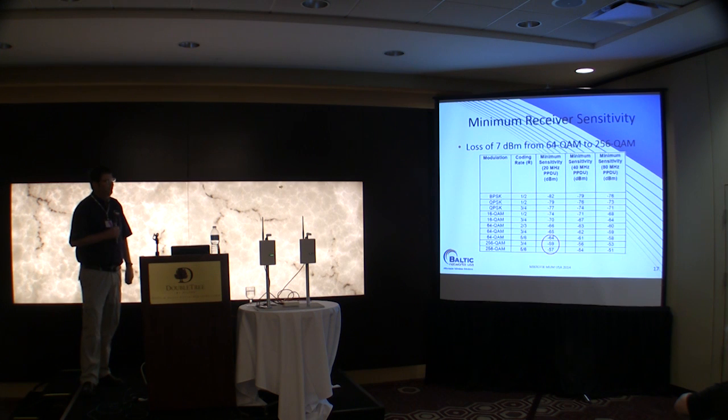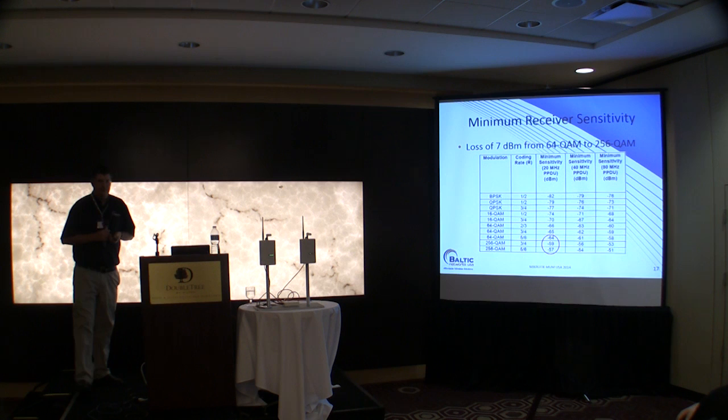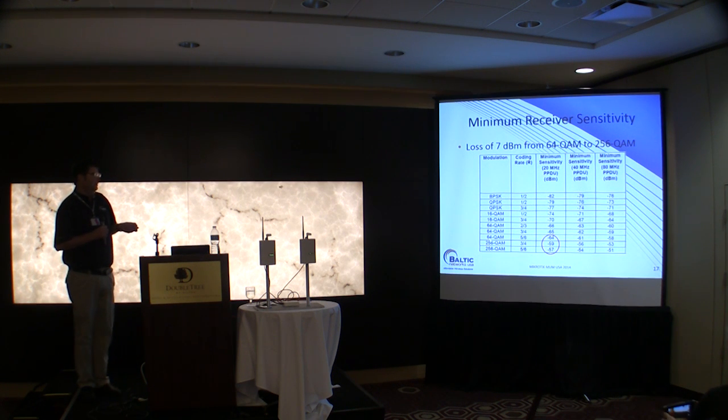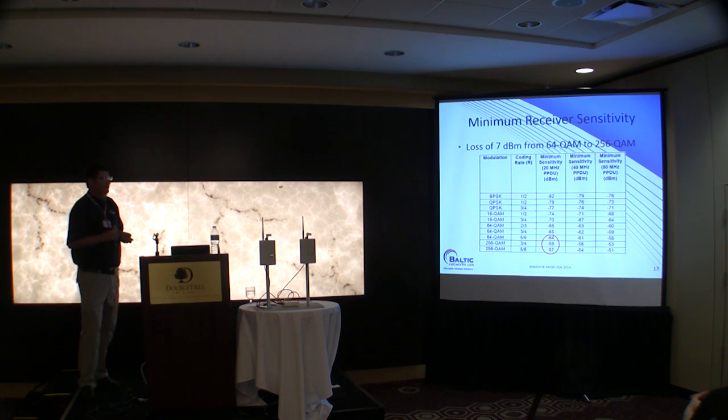So to the specs, the receiver sensitivity changes from 802.11n to AC. With 64 QAM, you'll see we had a negative 64. And again, these are specs. These aren't RouterBOARD specs. These are just the AC specs. With 256 QAM at full modulation, we go from 64 to 57. And that's a 20 megahertz channel. So you'll see that that means we need a higher power to basically run these types of higher modulation rates.